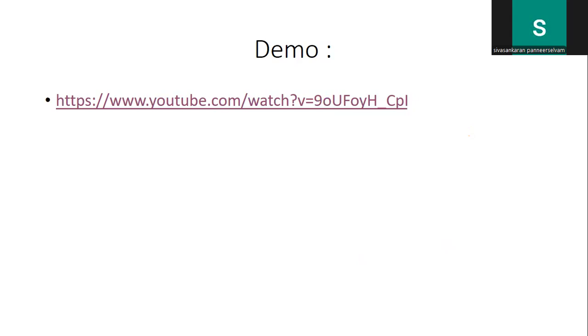According to this, one can see that we have a cylindrical slab of 30 millimeter by 60 millimeter length connected to another square slab of 30 millimeter and height 60 millimeter. Now let me show you how to construct the same. Using a line command with thickness of 0.35 millimeter, we will construct a 30 mm square shape first in the isometric projection.